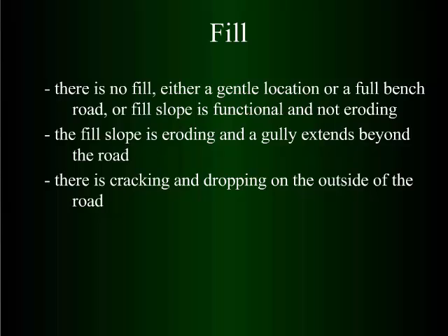And so if you see a tension crack, you've got to start looking. There's a reason why your fill is starting to move. You just need to try to identify what that is and correct it. Most times it has to do with water and getting the water off the road.